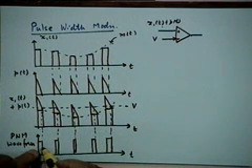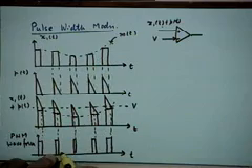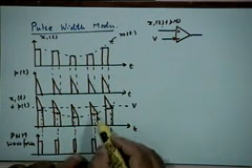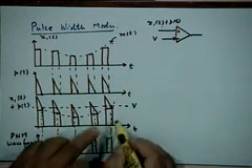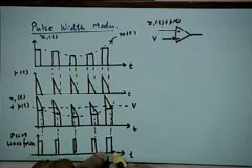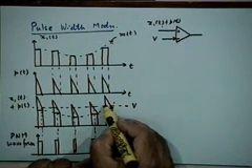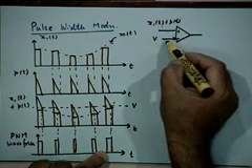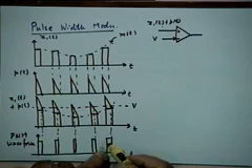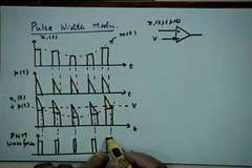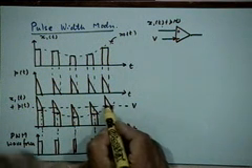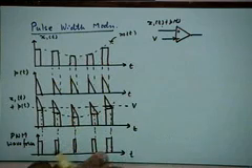So, you will get a large pulse width here, a smaller one here, and a still smaller one here. The pulse width will increase here again and increase further here, because during this time this voltage is greater than the reference voltage. So, you will get a pulse of constant amplitude, but whose duration will depend on the duration for which this remains above this threshold voltage.